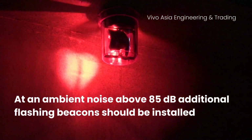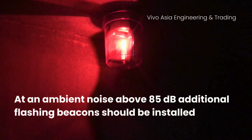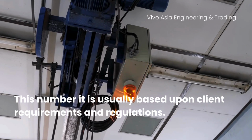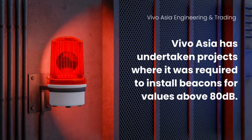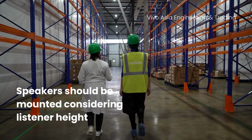At an ambient noise above 85 decibels, additional flashing beacons should be installed. It should be noted that while 85 decibels is generally acceptable, this number is usually based upon client requirements and regulations. Vivo Asia has undertaken projects where it was required to install beacons for values above 80 decibels. Speakers should be mounted considering listener height.